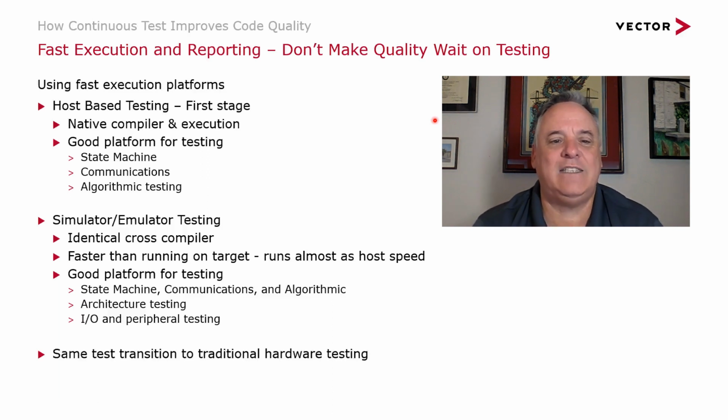And all these tests translate to when you're actually running on hardware, it's just very much slower because again, the discrepancy between the processor speeds, loading things onto the board, flashing, running over a slow JTAG, things like that can really slow down your testing. So when you're thinking about this type of thing, the faster the better.